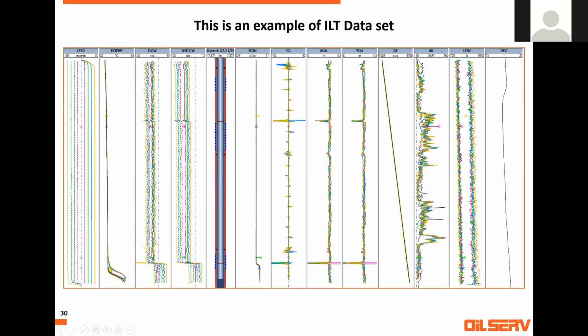The jump in temperature means the injection has stopped, and the well is back to geothermal below that level. That means none of the water is going to this perf. This perf is behind the tubing, and this perf is also behind the tubing, and this one is behind the tubing.